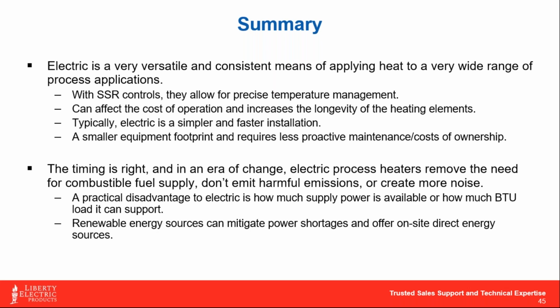Solid state relay controls, which I told you before I'm a big fan of, give you very precise temperature management, and they also help the longevity of your investment. If you're going to spend $20,000 on a process circulation heater, you'd like to have this thing around in 20 years. So the SCR more than pays for itself in the long run. Typically, electric is also going to take up less of a footprint, and you don't have the emissions issues, you don't have flammability or combustion issues.